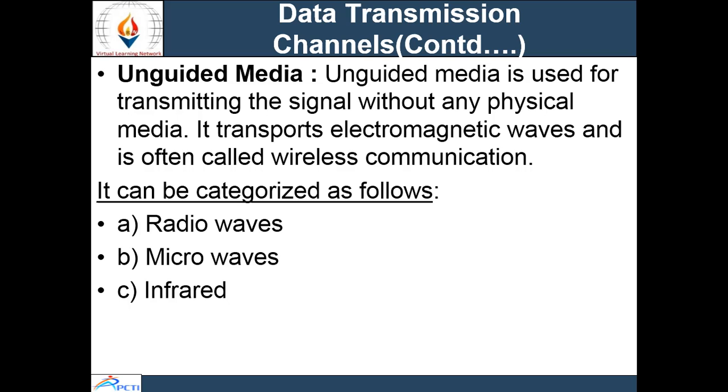It operates in the gigahertz range with data rates in order of hundreds of Mbps per channel. Telecommunication carriers and TV stations are the primary users of microwave transmission. An important form of microwave system is a satellite system, which is essentially a microwave system plus a large repeater in the sky.